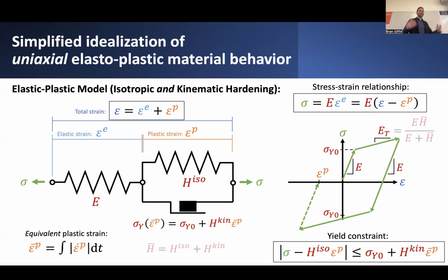It was a measure of how much total permanent deformation or plastic strain has accumulated in this slider element over potentially multiple cycles of deformation. If we introduce that dependence, then we got slightly different behavior, where rather than the yield stress of the material staying constant, it increased over time uniformly. And we called that behavior isotropic hardening.